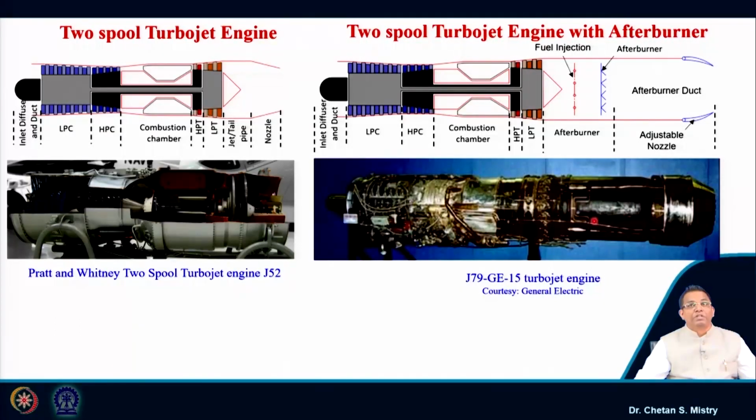Since my temperature at the exit of my afterburner, or before entering the nozzle, is very high, it requires a special kind of cooling. And if you recall, we have discussed the afterburner liner incorporation, where different kinds of cooling mechanisms are being used.